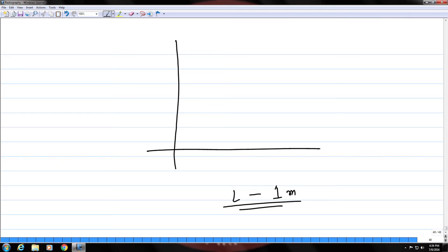So, this chart is in between this exposure chart or the exposure plots that you have. It is in between the exposure. So, this is in terms of times the current into the exposure time, and this has to be calibrated for a particular material against the thickness. Okay.